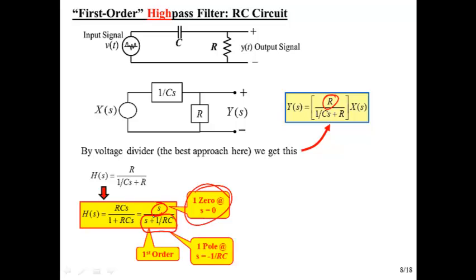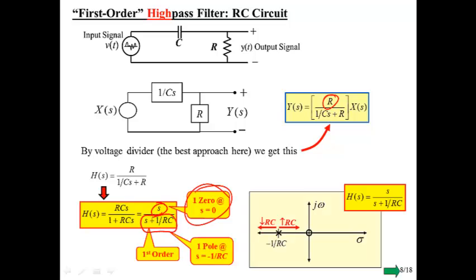And we get the same exact pole. We get a pole zero diagram that looks like this. So for the low pass, we had just this pole and we did not have the 0. For the high pass, we've got a 0 there. So now remember, we're going to find the frequency response, we cut along the j omega axis, and look what happens. That 0 ties down the frequency response to 0 at omega equal to 0, and therefore it keeps it low at low frequencies. And so that's exactly the behavior that we want from a high pass filter.